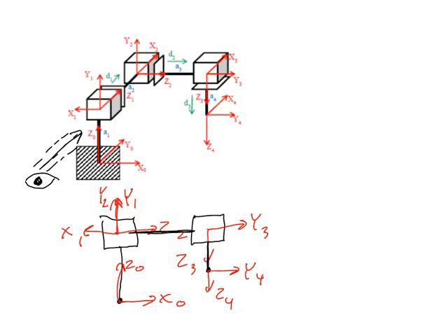Now, I'm also going to label on this picture some of the variables that we can see in the picture. For example, we can see that this link length is A1, just as it's labeled up here in the diagram. And we know that the distance between here and here is equal to the link length A3 plus however much this joint variable has been extended, D2.